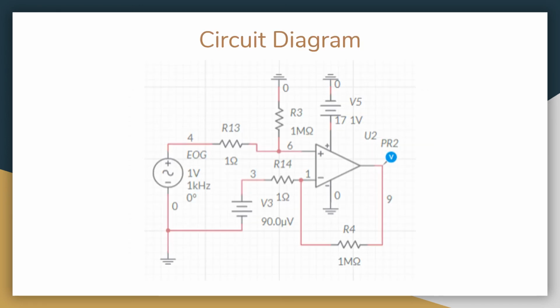This part of the circuit will interpret data from the EOG signal. The voltage input represents the signal received from the EOG device. There is a DC offset present to ensure that the majority of the data will be negative. Positive data will be present if there is sufficient eye movement present during the REM sleep, or if there are K complexes present.